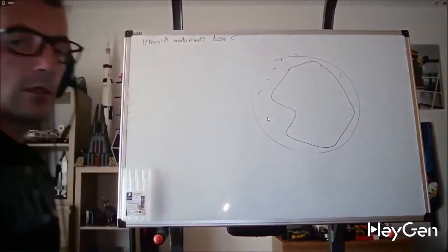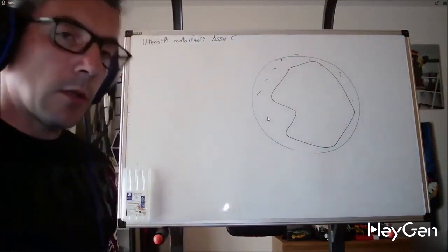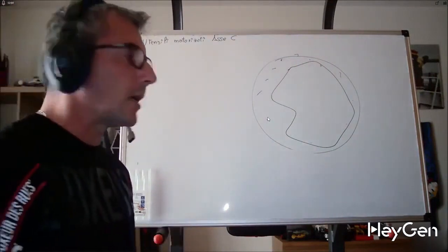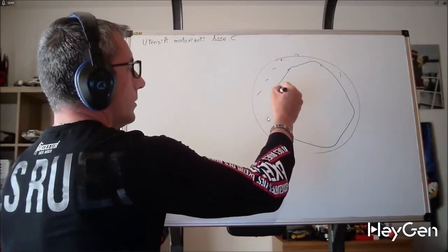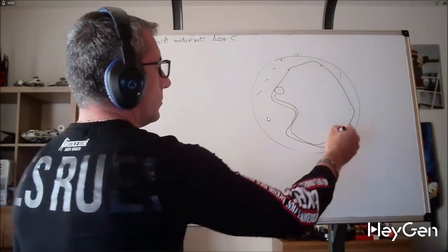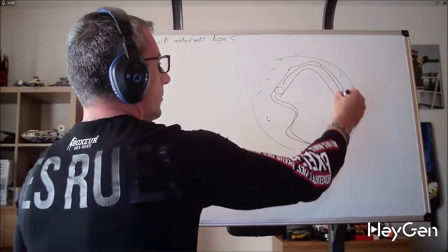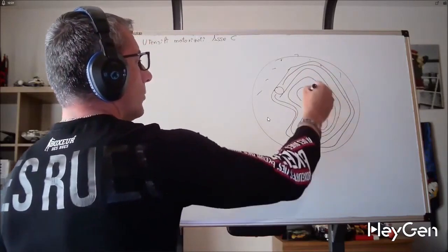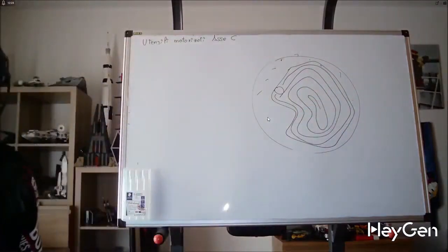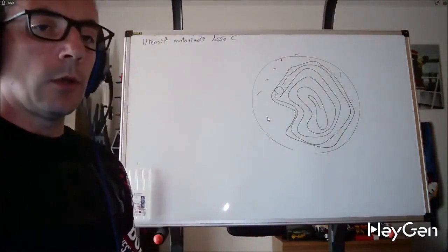There are no macros, at least on FANUC systems, so I'll stick to my experience. Correct me if I'm wrong, but there are no macros in the sense that if I outline my entire pocket with a mill, I then have to empty it out bit by bit. So I need to create an ISO program that's as long as the entire world. That's why I told you right away that I usually use conversational programming.